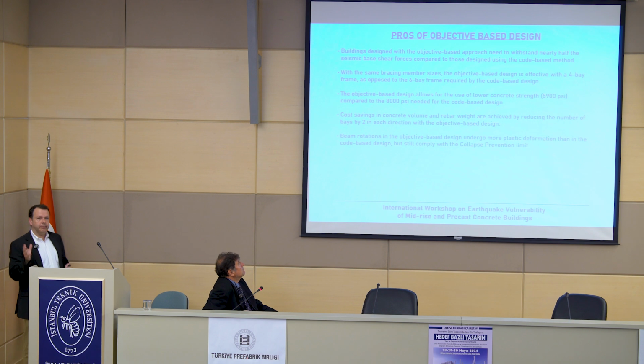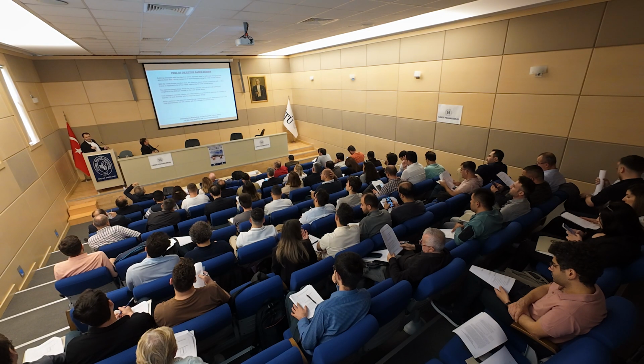So, a summary here set as advantages, but overall it's a summary. Buildings designed with objective-based approach need to withstand nearly half the seismic base shear forces compared to those designed using code-based method. That's one first conclusion. We saw 0.15 versus 0.07 for the seismic coefficient.